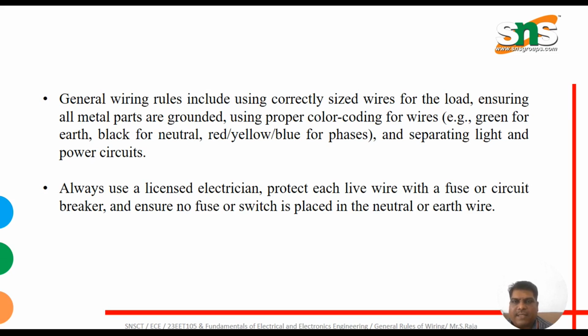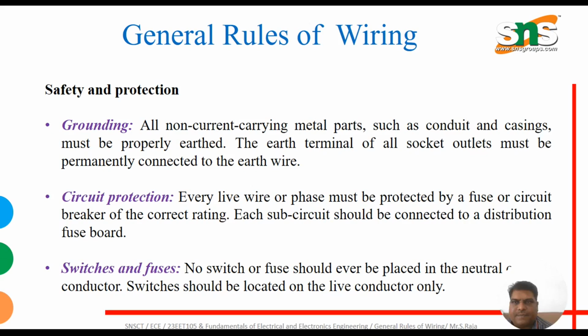Always use a licensed electrician to protect each live wire with a fuse or circuit breaker, and ensure no fuse or switch is placed in the neutral or earth wire. If you see in your classroom, the switches are available, but at the end of your classroom, that is, for the entire building, we have only the MCB at the main connection. This MCB or switch connection may be given by a licensed electrician for proper connection. So these are the general rules of wiring.